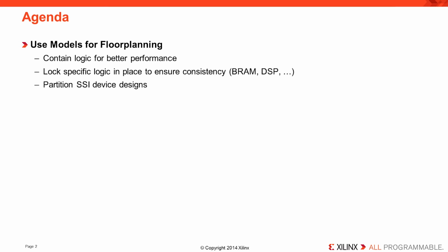Another use model is to use floor planning as a partitioning means for SSI devices. These stacked silicon interconnect devices actually have multiple silicon dies that have to be partitioned internally by the tools. You can floor plan your design to help that partitioning effort and to direct specific pieces of logic into the various SSI regions.